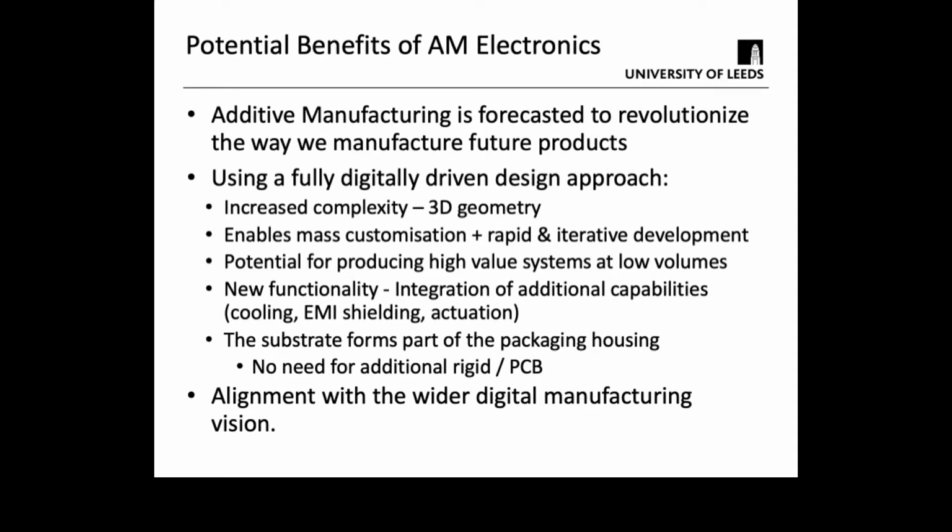Obviously, if you don't need tooling and templates, it enables mass customization, plus facilitates things like rapid and iterative product development. If you're not having to have upfront tooling costs and templates, you have the potential for producing high value systems economically at low volumes. And some of the examples I think you're going to see over the next couple of days are also people trying to integrate additional capabilities such as cooling, electromagnetic shielding, or incorporating movement actuation.